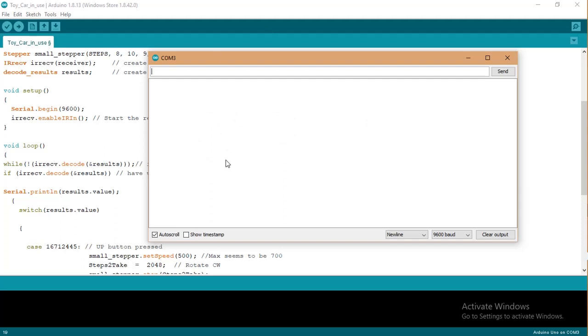This is now the serial monitor, so every data you want it to print is printed here, and when it's printed here, then you're able to interact with your program and see what's working well and what's not. So that's the serial monitor. That's why I used the Serial.begin, because we need to start it at a baud rate of 9600. Again, we will look at that deeply later on, but for now you just need to know this.